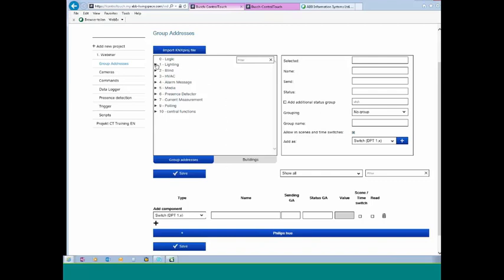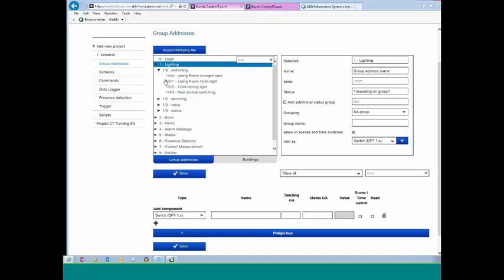This is very easy. So what you can do is to say, okay, at first, the target is I want to have a visualization of my living room. What I want to do is to control some lamps. I also want to control some blinds and, of course, maybe the heating. So in that case, you can open here the structure from your ETS. You can click on lighting. You can, of course, select directly the group addresses, or what you can do is to say, no, I go to the group address above, and this box here works like a filter function.